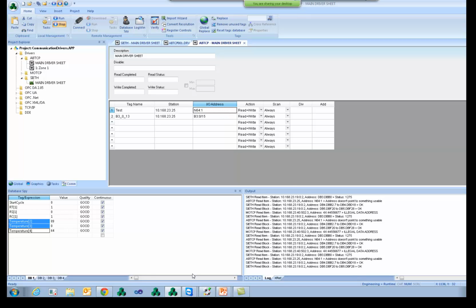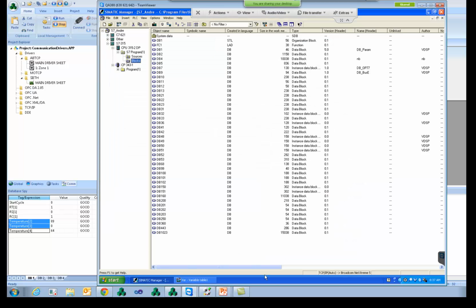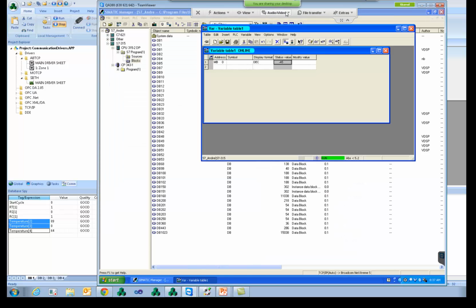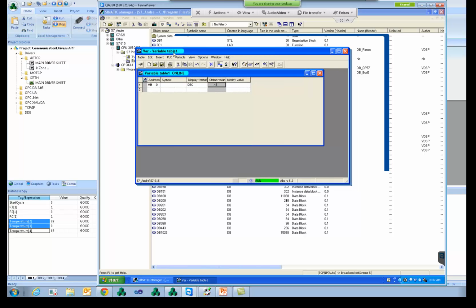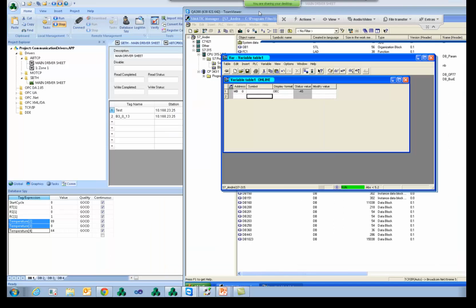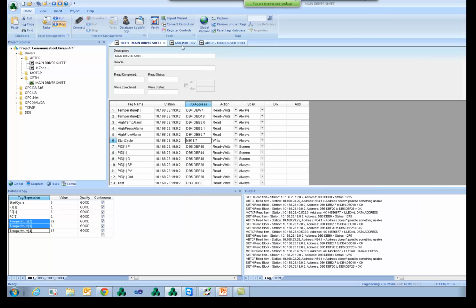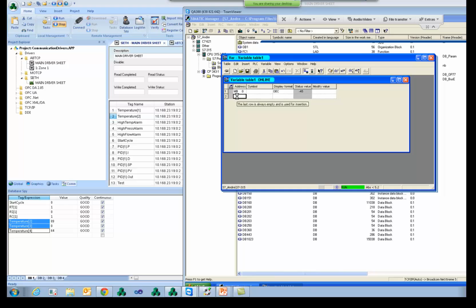Okay, so as a comparison here, I'm going to show another PLC that I have connected now. So this is a Simatic Siemens Step 7. I'm talking to a CPU S7 315. So here, if I open my Siemens driver, if I want to talk, let's say, to the DB4, B-Word 7, that's how I configure on the driver. And this is how I configure also on the Siemens software. So when I read this, I have here my value.